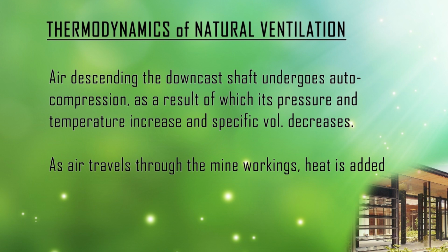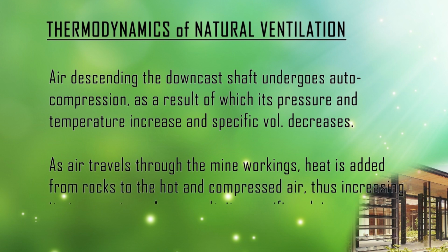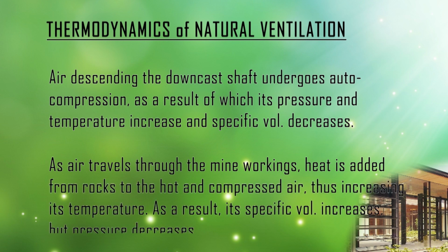Because due to auto compression there is the addition of heat, because this is an adiabatic process as it takes place at a very fast rate, and due to this the temperature becomes higher. Again, as air travels through the mine workings, heat is added from rocks to the hot and compressed air, thus increasing its temperature.